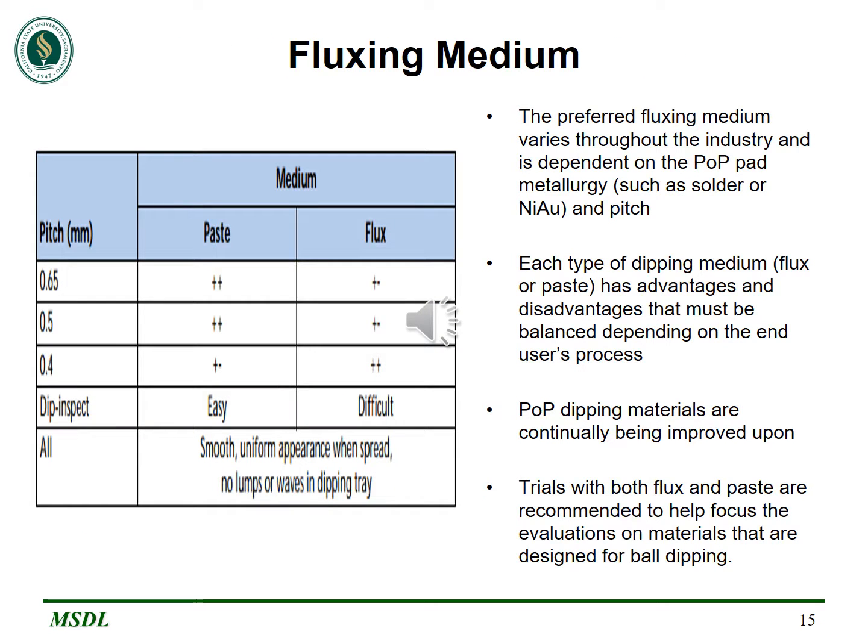Fluxing medium is normally applied over the ball which is used for attaching one package over the other package. The top memory is not attached to the PCB board but to a thin individual package. This has a significant limitation since paste cannot be effectively stencil printed onto the bottom package, which leaves ball dipping as a reasonable process available.